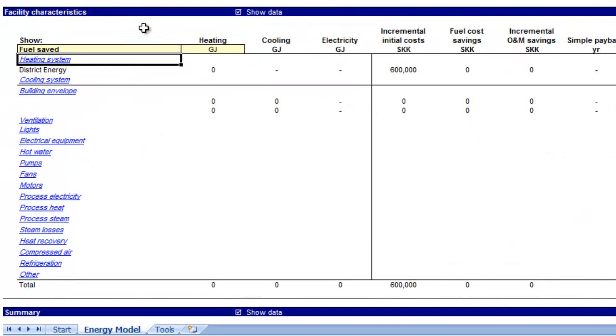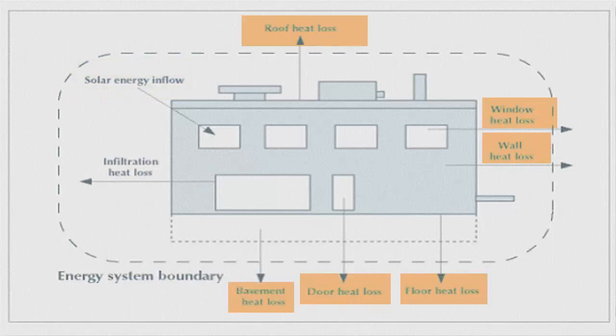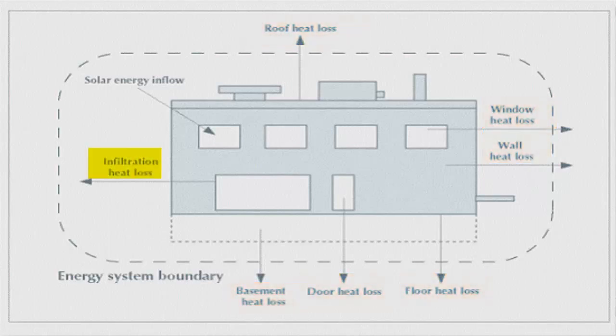The energy performance of a building envelope is influenced by a number of factors. For example, these may include design elements such as the physical orientation of the building and the amount of sunlight that penetrates into the interior living or workspaces. Other factors may also include the heat transfer characteristics and the location of the building, as well as envelope components including walls, windows, doors, floors, and the roof. The energy performance of a building may also be influenced by any natural air infiltration through the building envelope. The building envelope schematic shown here provides an overview.